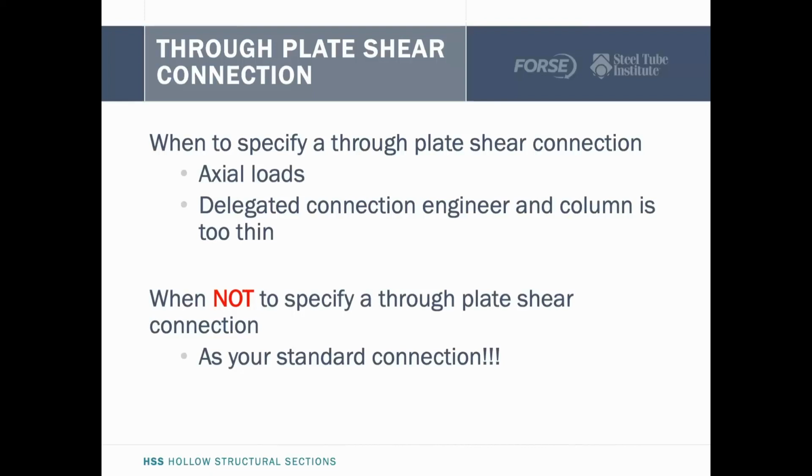Absolutely specify that. Obviously, if you're a connection designer and you don't have a lot of control over what the EOR has specified for the thickness of the material, then you might end up having to specify a through plate connection. My point here today is that we just don't want to specify it as our typical standard connection, you know, that detail that we pass from job to job to job when we're setting up a new job. We don't want this specified as our typical connection.